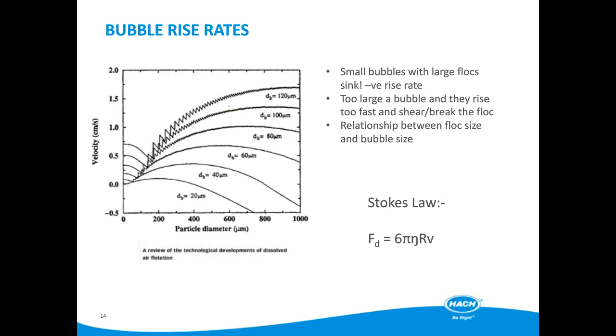This is due to smaller bubbles having a lower buoyancy, and their volume to surface area ratio reduces, meaning the drag on the bubble by the viscosity of the water increases with reducing size.